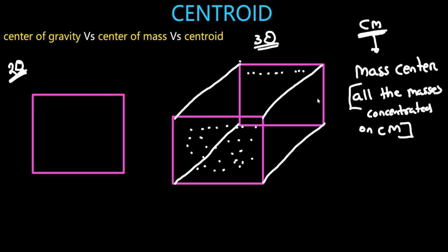Okay, see, in the starting of engineering mechanics, I told you one assumption. The first assumption was that in engineering mechanics, whatever object we are dealing with is a rigid body. And the second assumption, I had not said at that time. Now I'm saying the second assumption in engineering mechanics: a distributed force system can be considered as a single concentrated force.